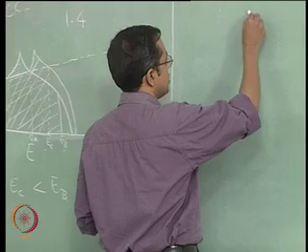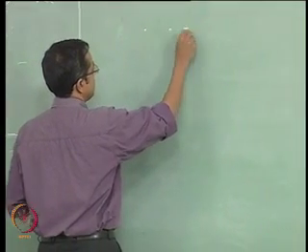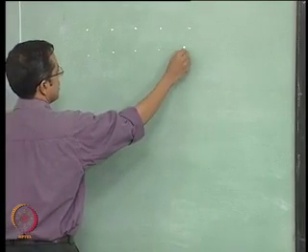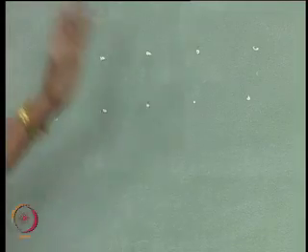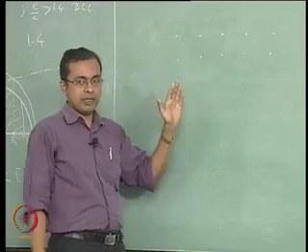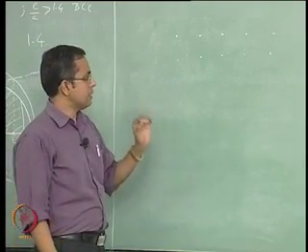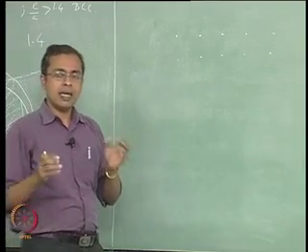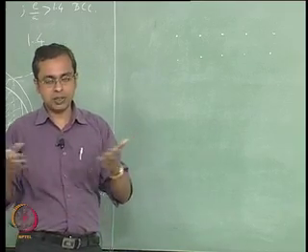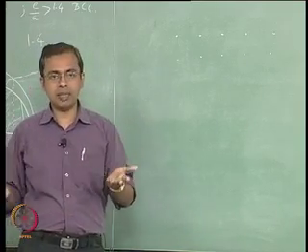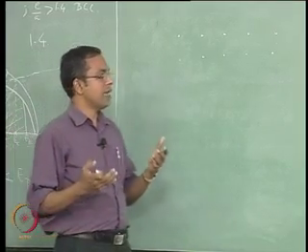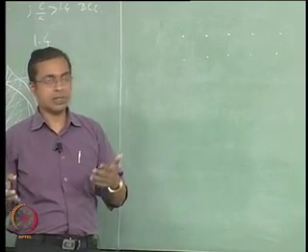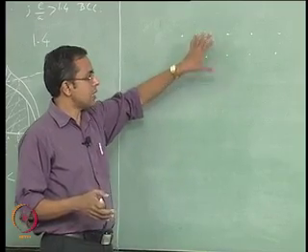Now in the structure of the solid, you have atoms at specific locations. This is how the atoms are, and around this is the free electron cloud, and mostly we are focused on the free electron cloud. But these atoms are not really static, they are not just sitting at exactly specific locations. Instead, based on the energy available to the system, they are in a position to vibrate about their mean position, and this is an important way in which they gain energy as you raise the temperature, and they also release energy as you lower the temperature. So atoms are in a position to